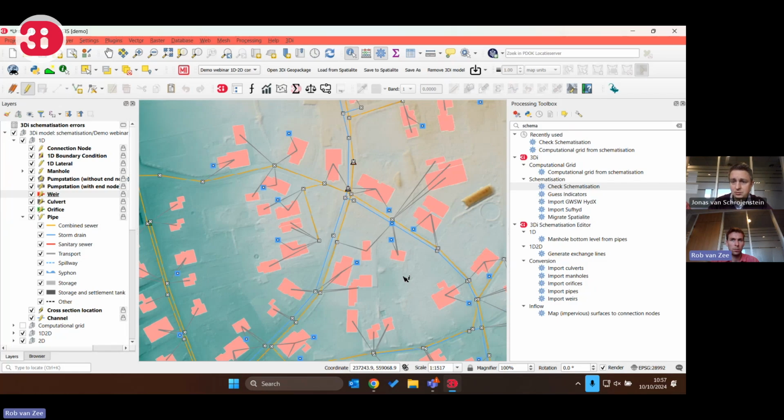To be honest, I think the calibration of your model, especially if you have 1D, 2D, I'm not talking about 0D, 1D, will be more towards infiltration values, and friction values on overland flow will have a higher impact on how much water is standing on the streets.